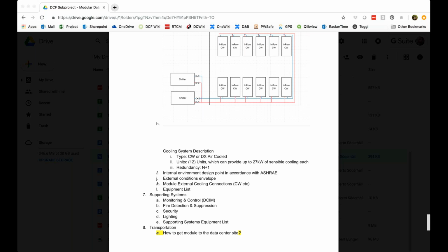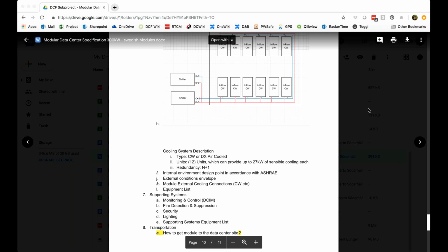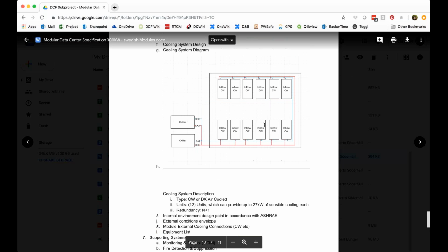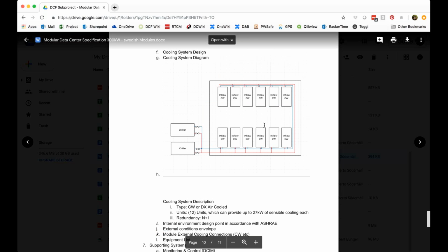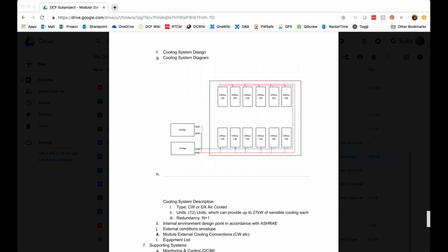But is it necessary to show 3 options even here, you think, Brevin? Have I lost him again? Yeah, I don't know what the options would be. Generally, for chilled water like this, you're going to have n plus 1 CRAC units or CRAHs, and then n plus 1 chillers.